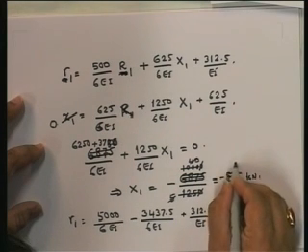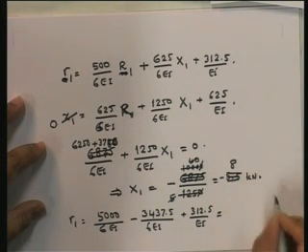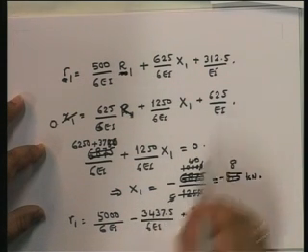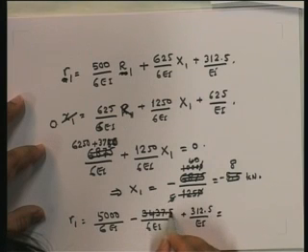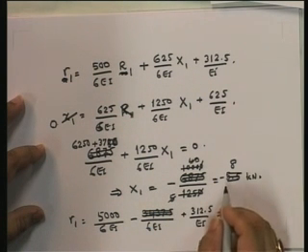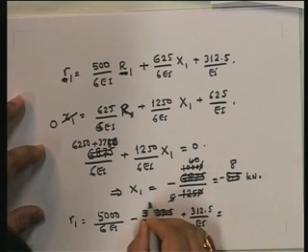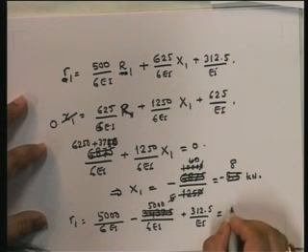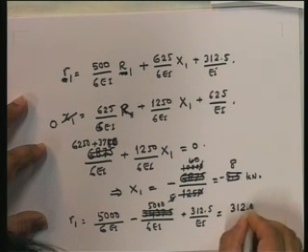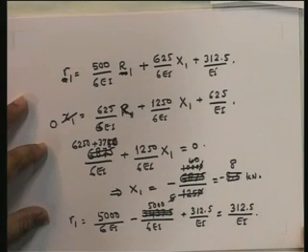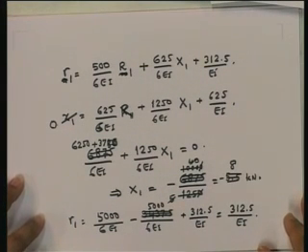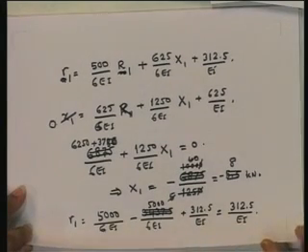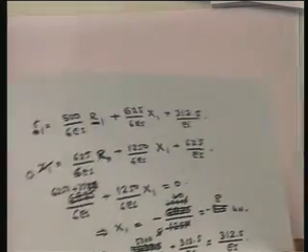8. This is minus 8 kilonewtons, and so when you do 8, you get 205,000, and what you're left with is 312 upon EI. Okay. And that is your R1. So you know your R1, you know the sway. Okay, so you found out your sway.